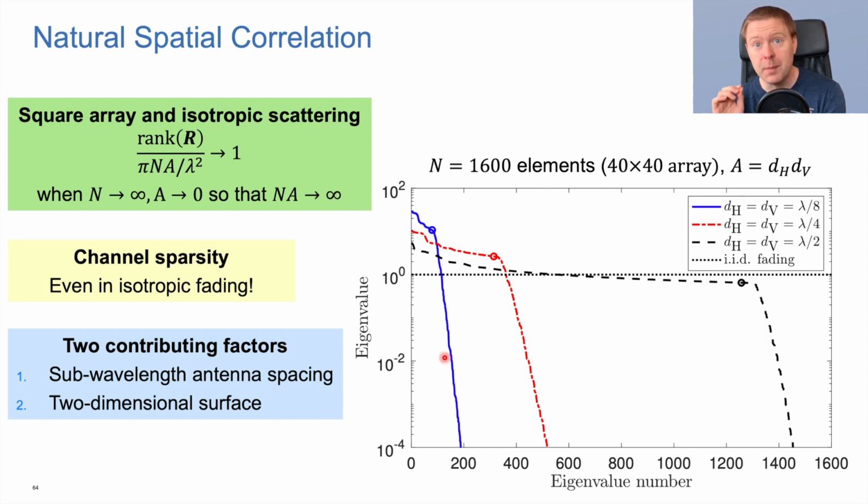So we are oversampling a space. Why do we do that? Well, we do it because we want to be able to spread out the signal energy more. But that is not providing us with the better ability to actually send more signals, because that is determined still by the spatial degrees of freedom, but only the ability to steer signals better and get a power gain from that.